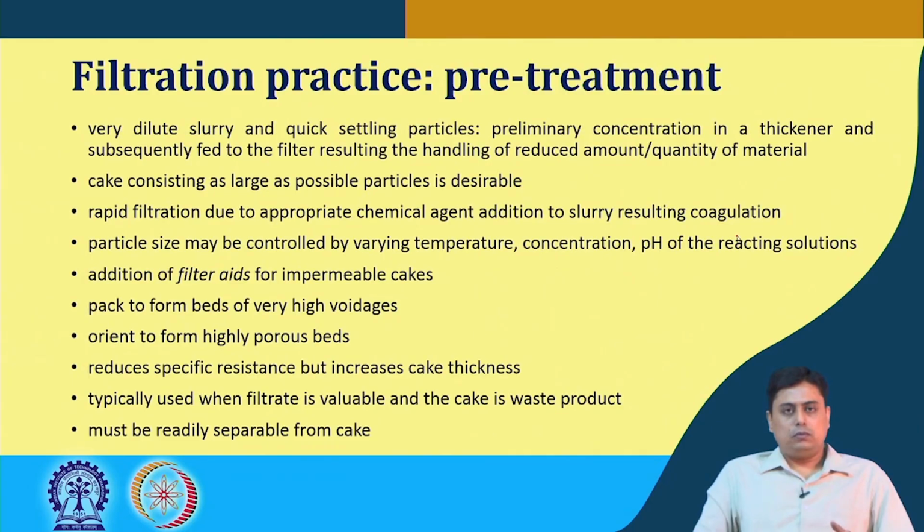So, we have mentioned there is pretreatment whenever that is required. When there is a very dilute slurry and quick settling particles are there, then it is logical, and in fact the pretreatment happens in a thickener to concentrate that solution or the suspension. Then you can handle a reduced amount of the slurry.